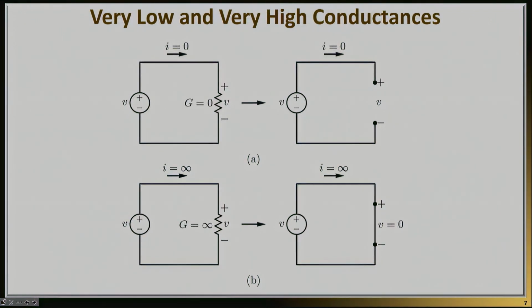Very similar things can be stated from the point of view of a conductance. When your conductance is basically equal to 0, it means nothing is being conducted, so essentially you have an open. Where your conductance is infinite, it means that there is basically 0 resistance to current, and therefore you have a short circuit.